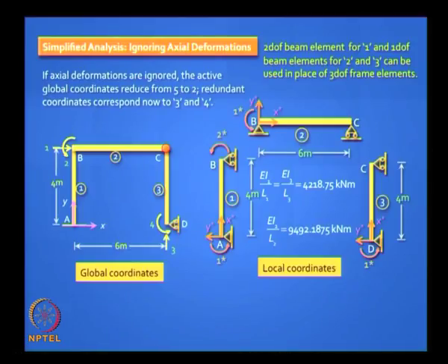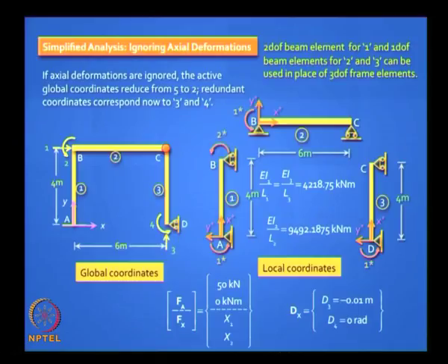For element 1 you still have 2 degrees of freedom, but because we want to take advantage of the internal hinge at C, I put a roller support there, so I have only 1 degree of freedom, and my FA and FX vectors are easy to calculate. It is smaller, much easier to work out. Dx is the same, only thing is earlier we wrote D6, D7, now we write D3, D4.